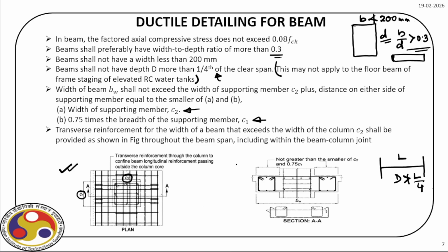Now you can see the detailing here, this detailing, and here we have to follow to ensure that proper reinforcement is placed along with longitudinal and transverse bars with proper confinement within the beam and column section. The idea is it should transfer load from beam to column, and particularly when there will be large deformation, this load transfer should be proper.